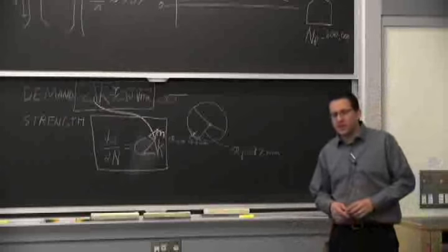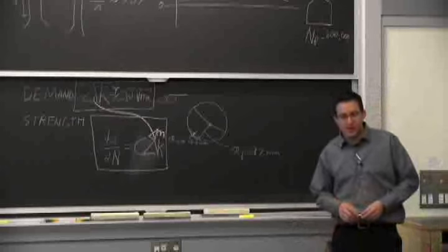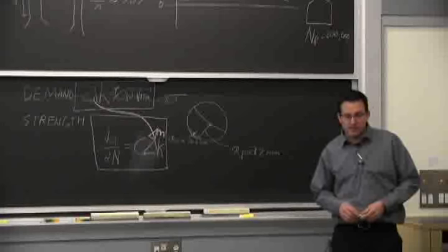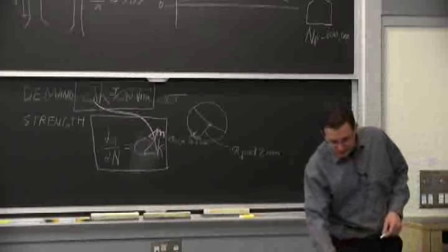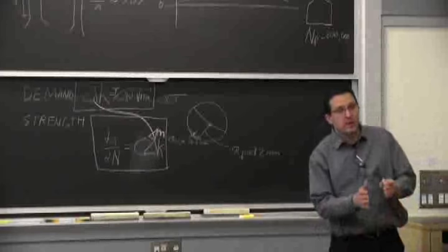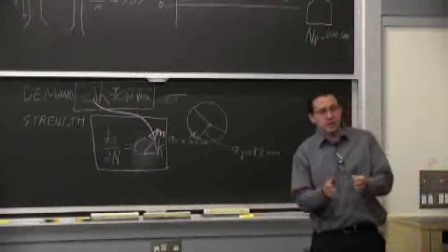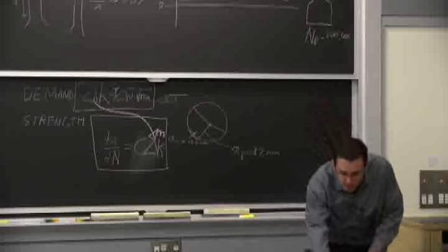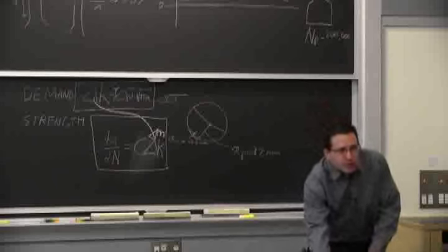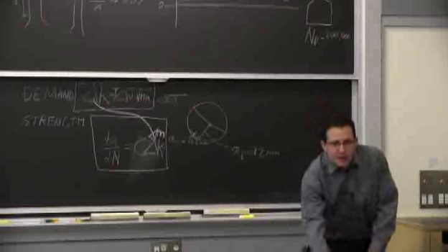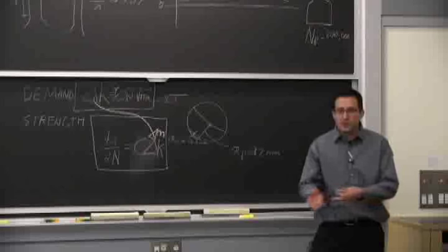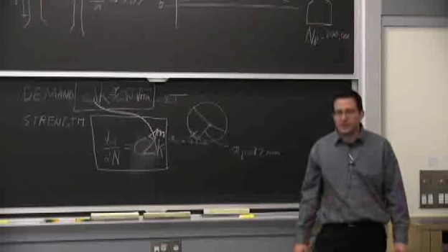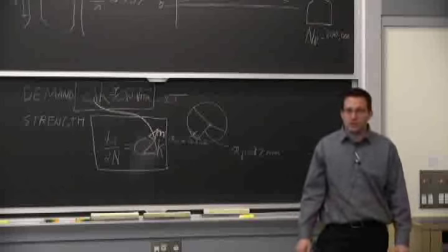There was a question, I believe, last class about striations in plastics. At the end, the plastic will go through the same process as here as far as opening and closing, opening and closing. It's just a question of whether you're going to see little ridges on it. It's nice to see them, but if you don't, you still have where the crack started, where it ended, and you have some idea how much time it took to get from one point to the other.